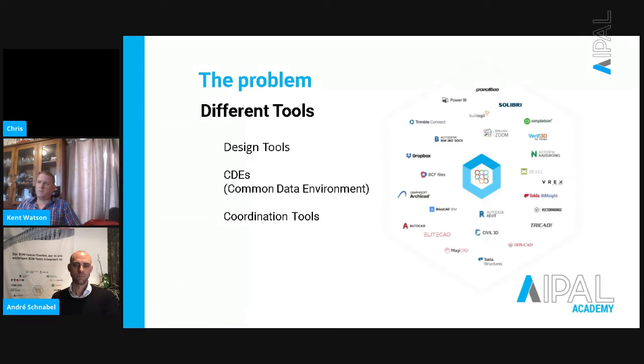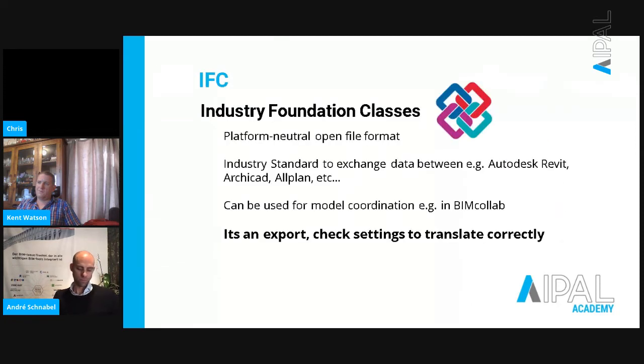And at the end of the day, the BIM coordinator needs to bring everything together in a federated model. And of course, Revit files and ArchiCAD files, they don't really like each other. So we need something in between, a translation or a common base. And that is the Industry Foundation Classes, IFC. This is nothing really new.